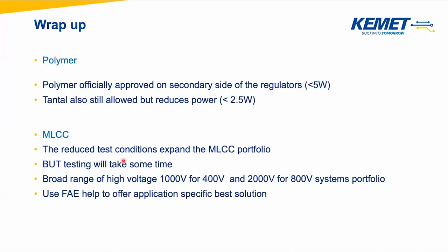For MLCC, this reduced test condition that is now given in the latest revision will definitely expand the MLCC portfolio. But testing will take some time. So we are in a discussion right now, and we're preparing testing. But you see it's at 2 times 1000 volt, and we're currently checking out our option with higher temperatures. Then we have to take 100 parts, and they have to have special PCB, so we can only have one chip one time in one slot. So we'll slow down the testing, not as fast as we typically work. But we keep you updated.